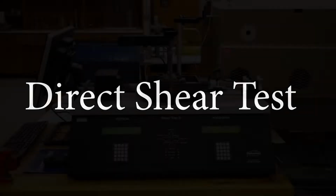Hello and welcome. In this lab we will be performing a direct shear test on silica sand to determine the friction angle and cohesion intercept. This test covers standards ASTM D3080 and AASHTO T236.